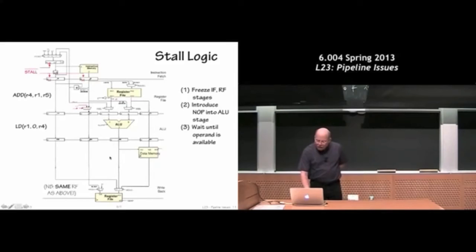So what we have here is a situation where we have to be very explicit. And so we put in this no-op just to make sure it's not inventing something, not good to do. In this case, affecting the contents of main memory, or perhaps writing a random value into a random register. Those are all bad ideas. So we put in a no-op that makes sure that no state will be changed as a result of saying, do anything you want. Okay, so then as things move forward, we put a no-op into the ALU stage, and the load proceeds, and we're all set.